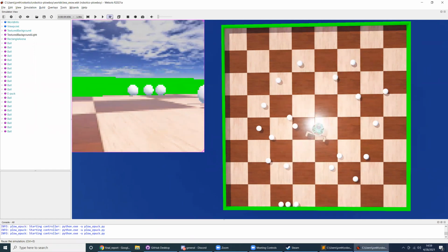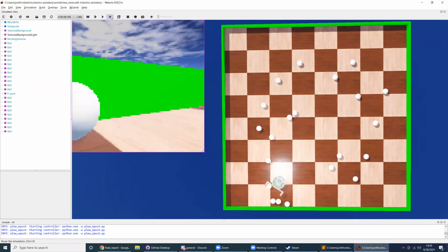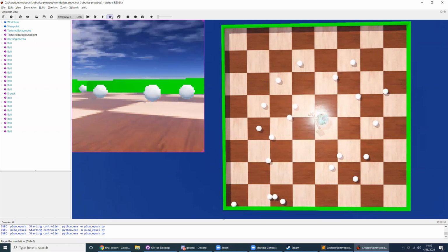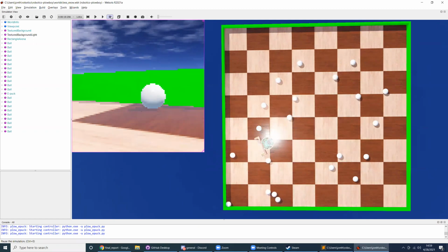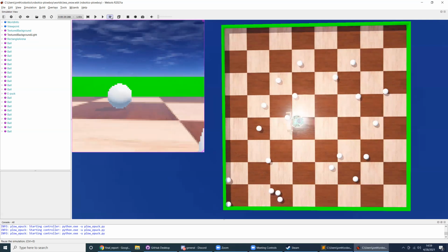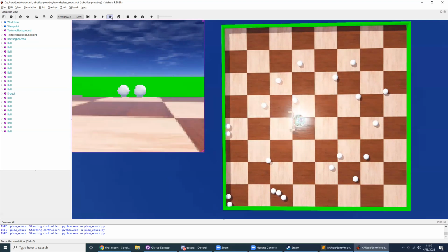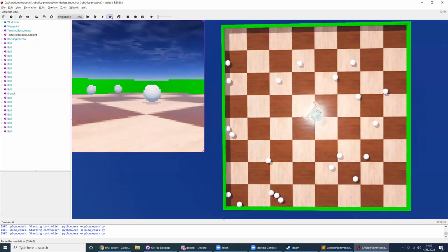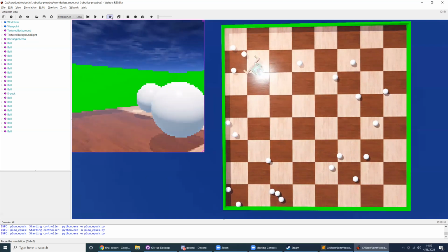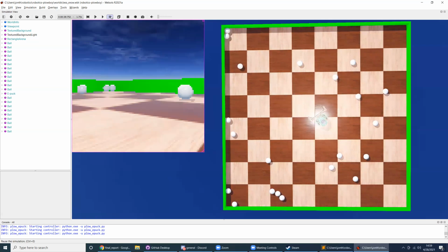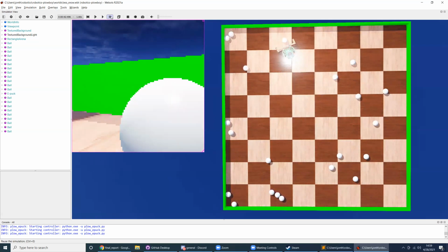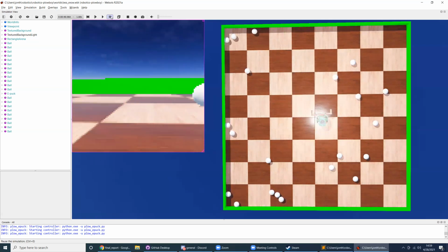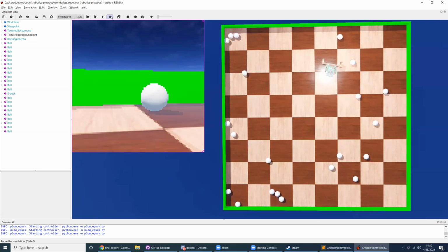All right, so our world, as you can see, is made up of these little snowballs that can be pushed around by our plow, and the world is surrounded by a boundary line that is colored. And the way that we detect snow and plow it is using a camera fixed to the flashlight on the front of the robot. And the frame is split into three different chunks to know whether the snow is in front, to the left, or to the right of us.